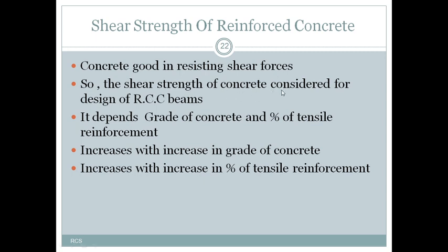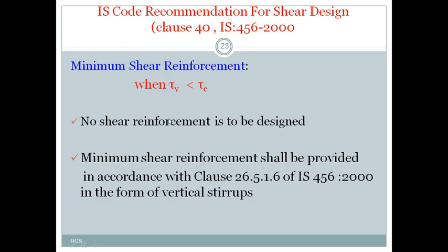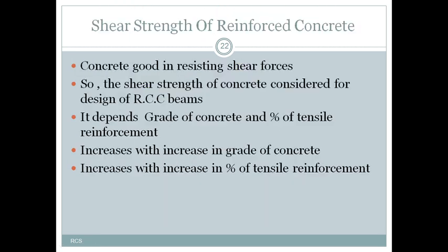The shear strength of RCC depends majorly on the grade of concrete and the percentage of tensile reinforcement. If the grade of concrete increases, the shear strength of the concrete also increases. If the percentage of tensile reinforcement increases, the shear strength of the concrete also increases.